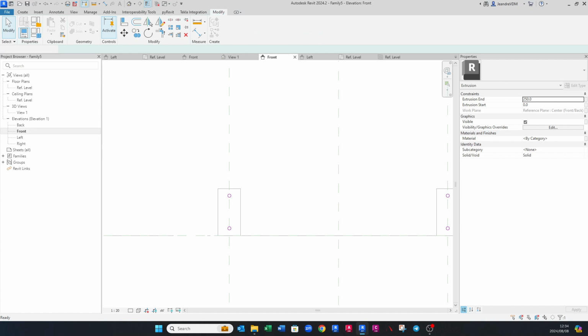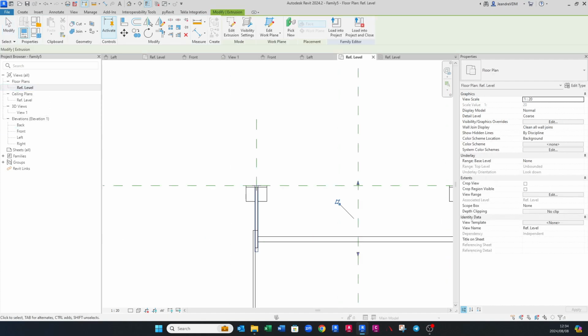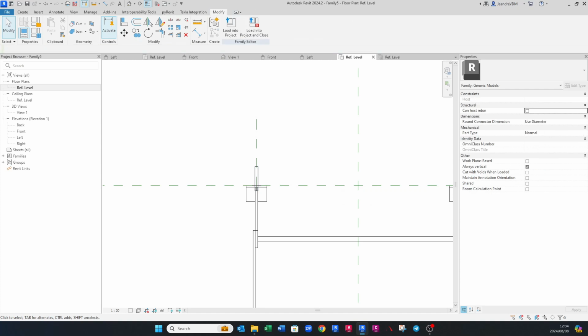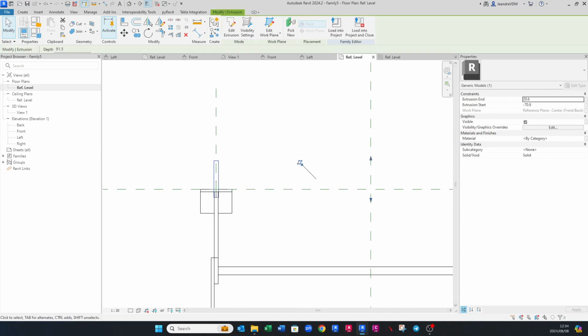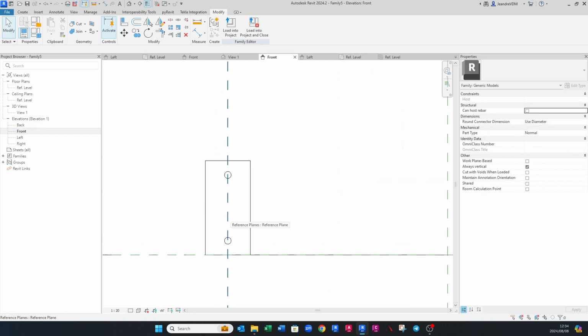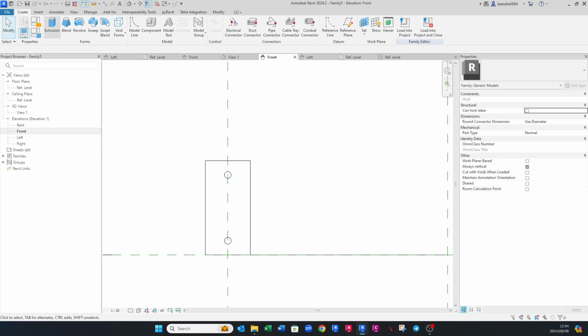There we go. So, okay, we go to our reference again. Now this is a bolt. We want the bolt to go into the fixing area, which could be anything, a wall, concrete, whatever your fixing detail is. Front elevation again. And now what I want to do is draw in the plate that actually connects to the vertical plate. So we're going to create extrusion again.